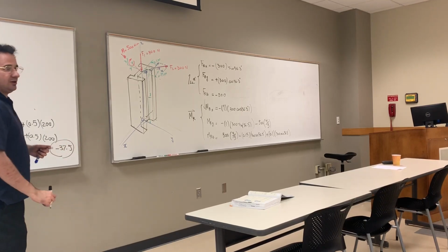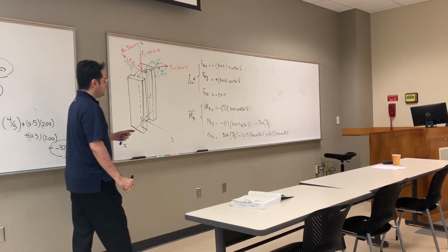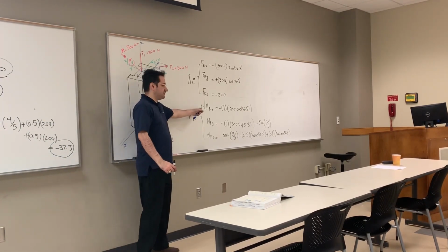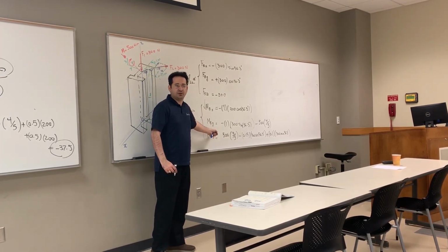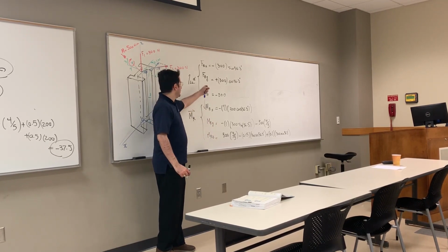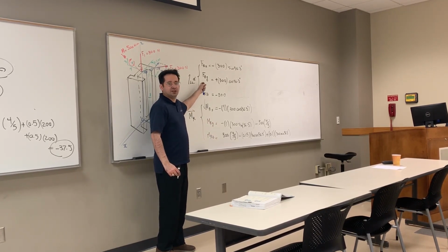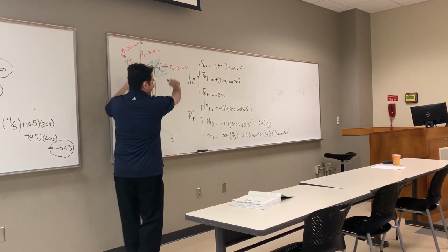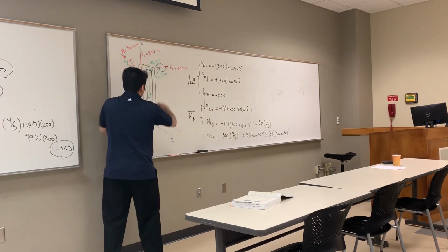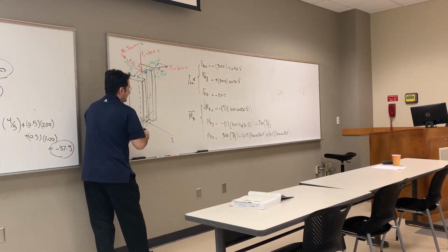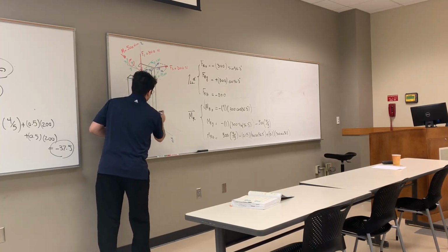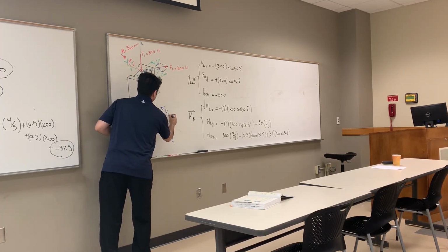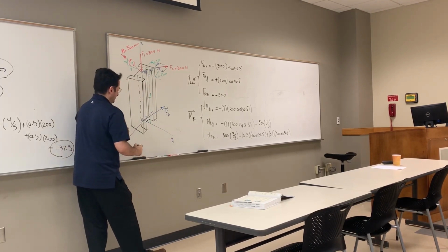So at the end, I have one. This is not three vectors. This is just one, the x, y, z component in Cartesian form. One moment and one force. So no matter how many forces or moments you have, you can eliminate them all and put here one force, like that, F resultant, and one moment.